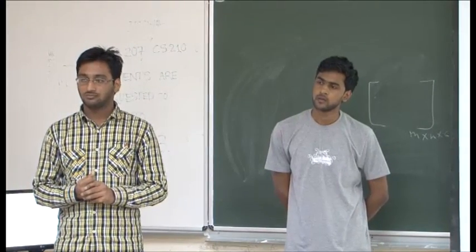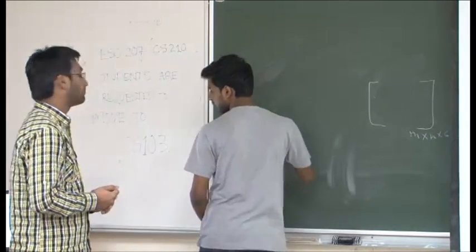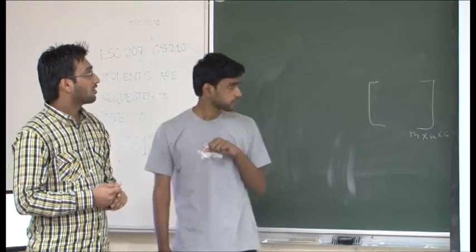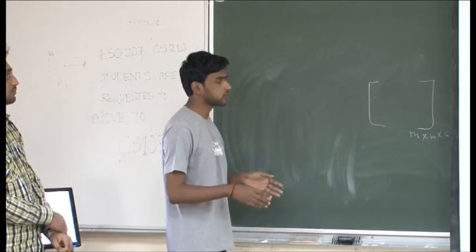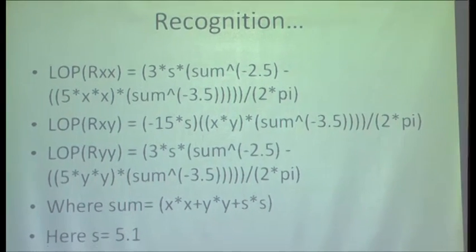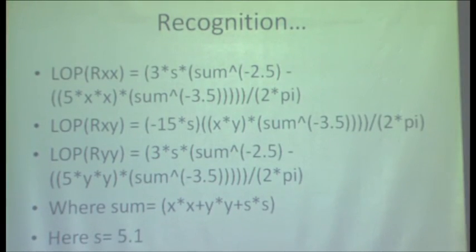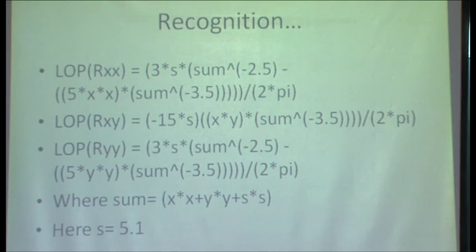So optimization. And what is here? Basically, the image we have been given has a wide range of intensity. So basically, we are using a bandpass filter. It is a filter using, just like a LoG, a measure of Gaussian. It will be a real number, right? Then we will make it binary.